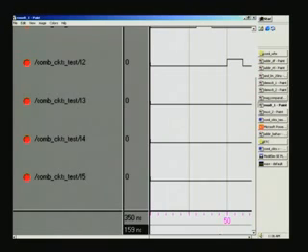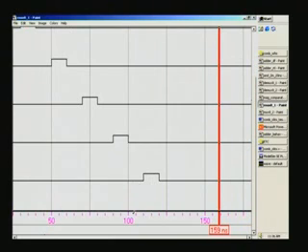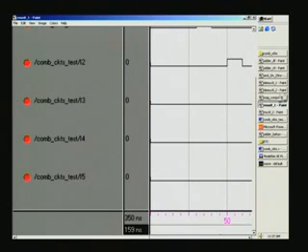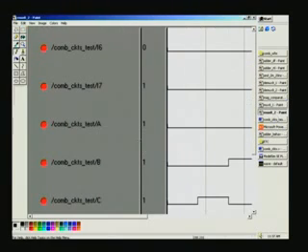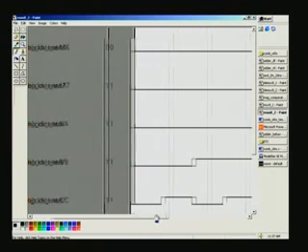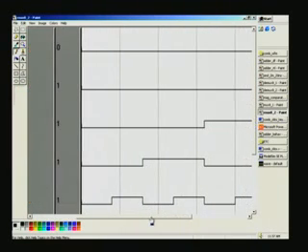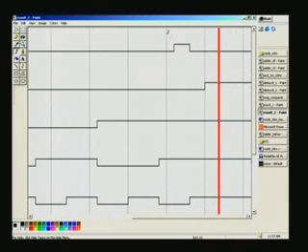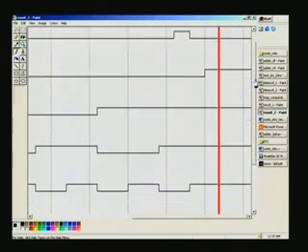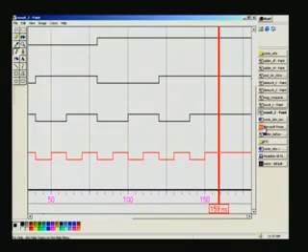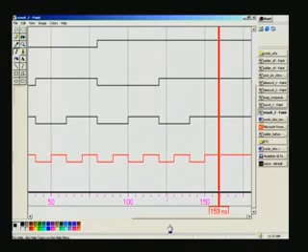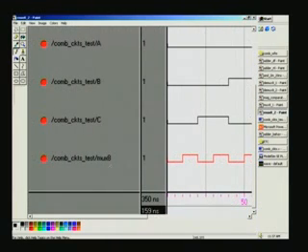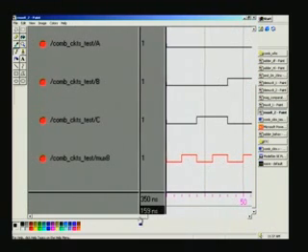This waveform came beyond 100 nanoseconds. Just remember, this is corresponding to I5. So in this you have I6, it must be somewhere, it's coming here, right? And that is precisely what you have here at the output, mux 8. So this was the very first pulse of I0, then I1. So that is precisely what you are having here.